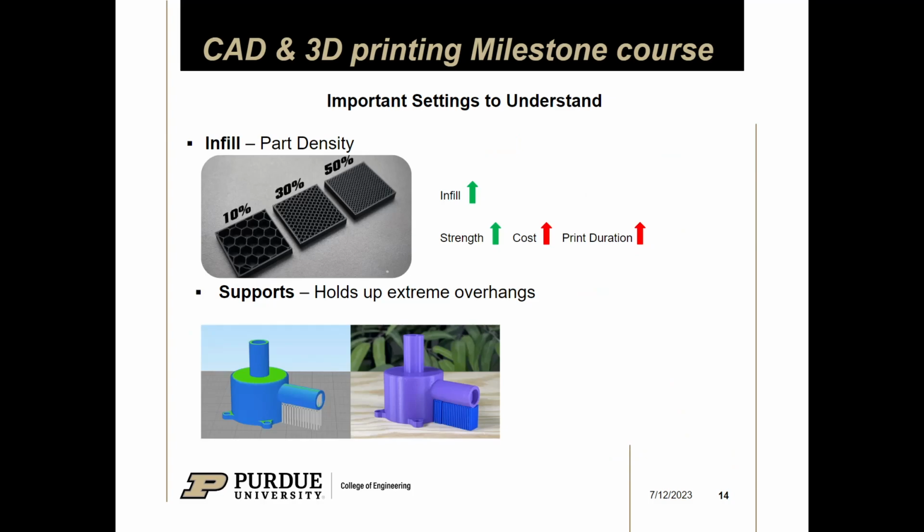The other important thing to note is infill. Most 3D printed parts are actually hollow, if you didn't know that. This saves on material and printing time because a lot of the inner material is not super necessary structurally, right? The main structural benefit you get is from the number of perimeters, because that adds a lot of rigidity to a certain extent.